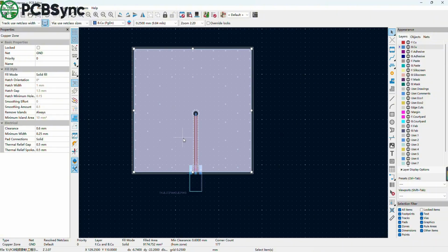On both sides of the feed line, you can see many rows of grounding vias. These vias help connect the upper and lower reference grounds and restrict the return path and edge radiation near the feed line. In this kind of antenna design, the patch size, feed line length, feed line width, dielectric thickness, and material DK all affect the final resonant frequency and input impedance.